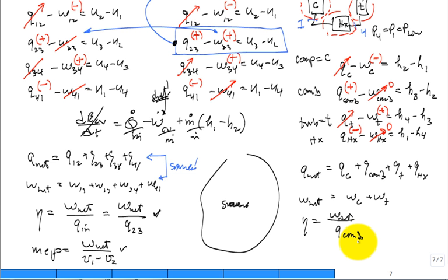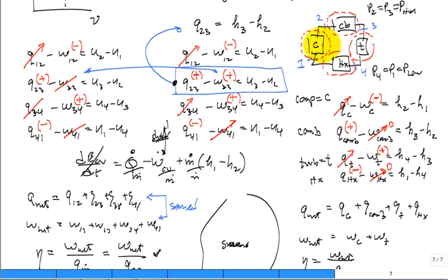There's another one for this cycle. It's the BWR. We saw it in the vapor power cycles, in the Rankine cycle, didn't we? What is the BWR? Back work ratio. There's typically a shaft. This turbine and the compressor are connected by a shaft. And some of the power out of that turbine has to go back and feed the compressor.